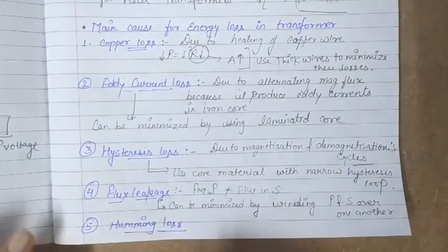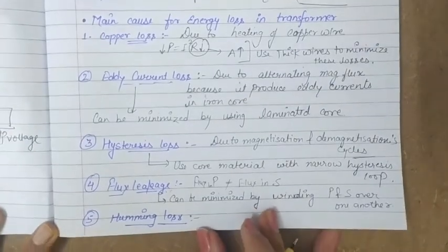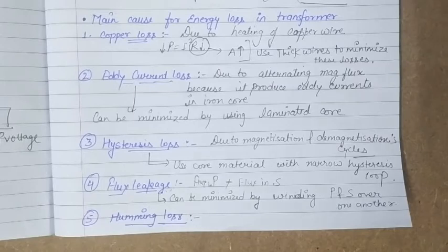When the transformer is working and there is alternating voltage present in the transformer, in that case the core changes its size minutely, meaning slightly there is a change in the length, in the size of the core. It increases and decreases its size, a very small change in size, just as the alternating voltage has cycles, in that same manner the size of the core will change slightly, a very minute change.